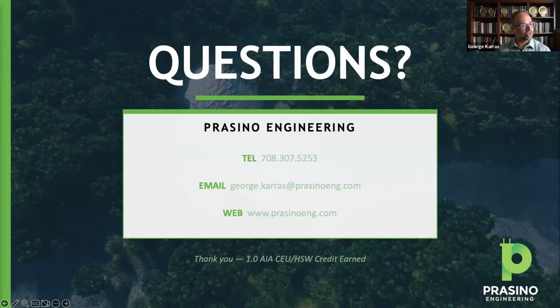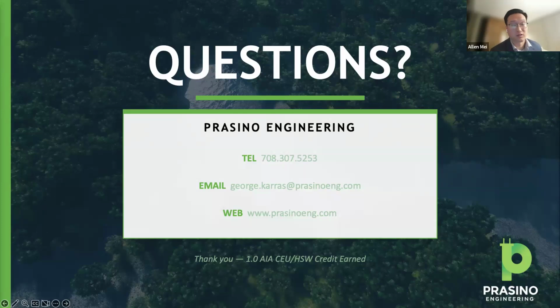Awesome. There's another one. Can you further describe the difficulty in meeting the efficiency requirements of IECC prescriptive? Well, IECC actually got rid of the mandatory label. If you look at IECC 2018, they put mandatory or prescriptive next to the provision. They got rid of that in IECC 2021 because they moved the mandatory table to the C407 chapter. The reason IECC is generally a lot more difficult to comply with is that they made so many more provisions mandatory. For example, occupancy standby is prescriptive in 90.1, but it's mandatory in IECC. Energy recovery is all mandatory in IECC, but prescriptive in 90.1. And also,